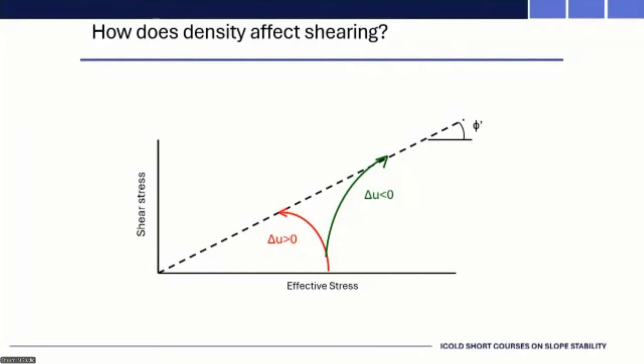Whereas the curve on the left, you're generating positive pore pressures, which is pushing you to the left in stress space. You reach that limiting condition, in this case, way before you would in a drained test. And this is even in the absence of super contractive behavior, when you actually get a limiting shear stress even before you get to that friction angle, as we'll see later.